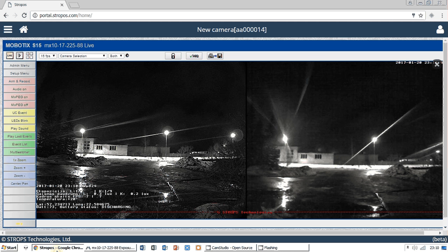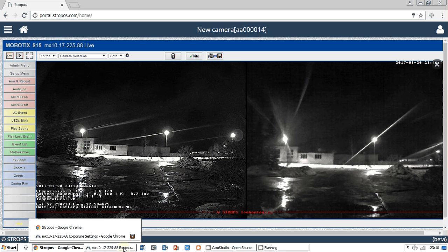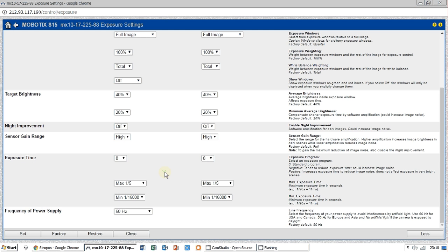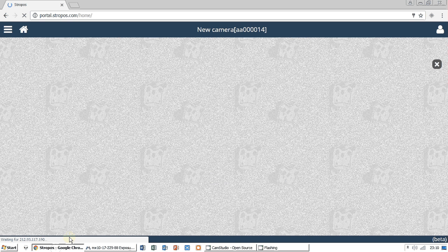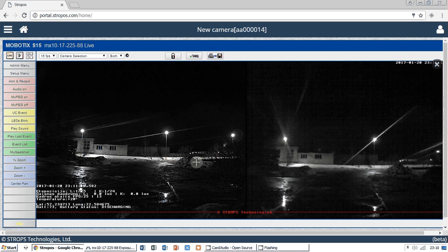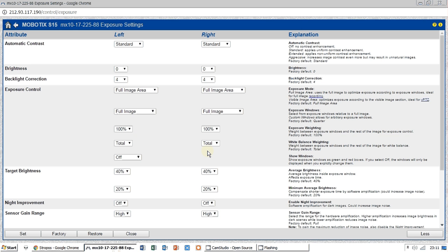In low light conditions, it's not that good when a car is passing very fast and people run, and you will see blurry moving objects in the video. What I do, we can give roughly about 1/3 second, and here as well. Okay, the picture will be a bit darker, but you will get nice, crisper details on moving objects in low light conditions.